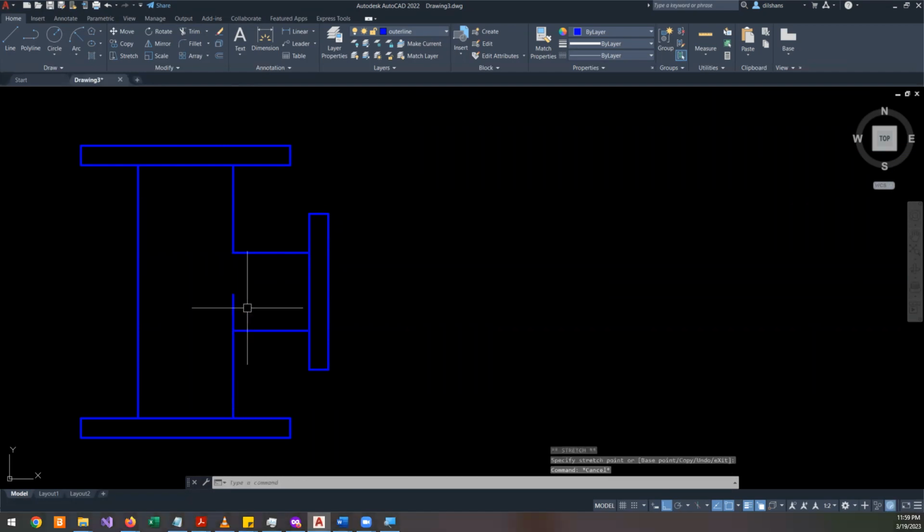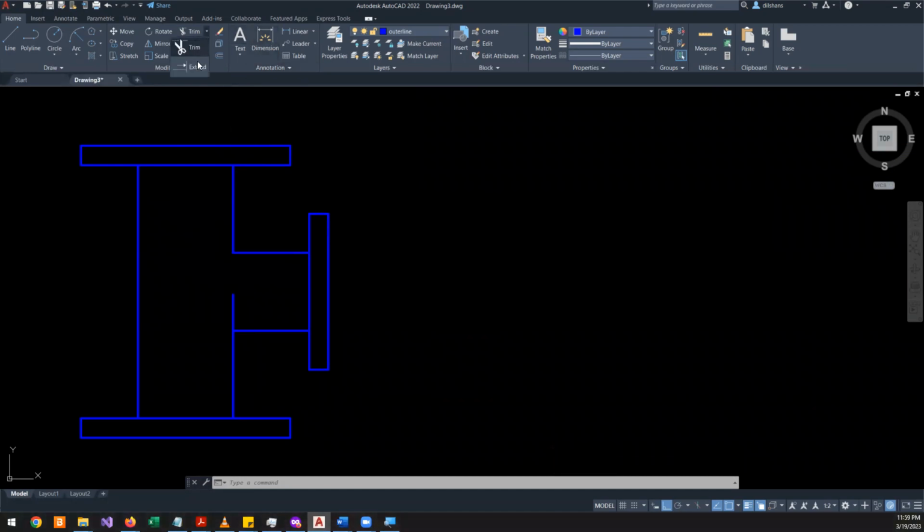Okay, I'm going to load you with one more piece of information. Let's say you are inside the trim command, but you want to extend instead of trimming. You can temporarily shift to the reverse. If you are inside the trim, you can quickly change to the extend by holding the shift key down. So I am inside the trim. When I'm not holding the shift key down, you can trim. If I press and hold the shift key, you are extending. See?